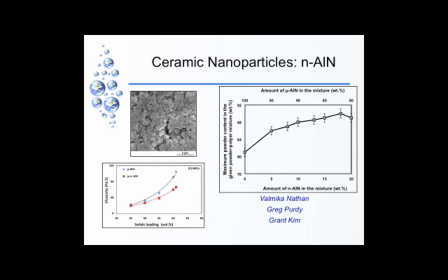Here is viscosity plotted as a function of solids loading. If packing fraction increases, what did you learn when you were dealing with mixtures? What happens when the packing fraction increases? What happens to the viscosity? Now, what about the maximum packing fraction? If that increases, what happens to the viscosity? As it goes up, that phi c increases, and so viscosity actually goes down.